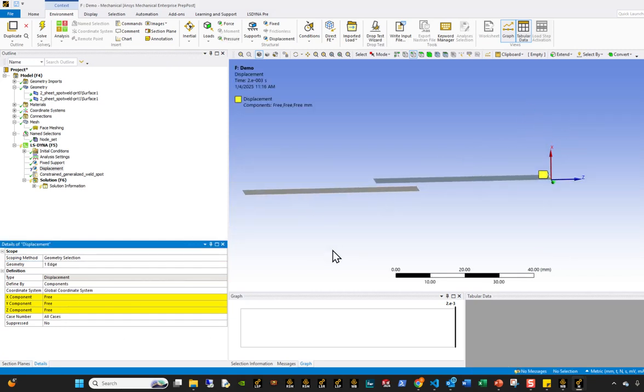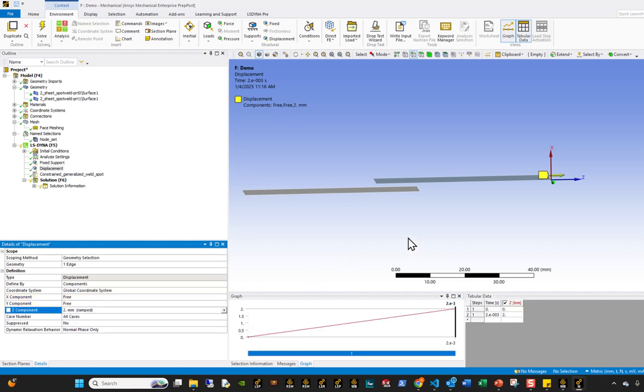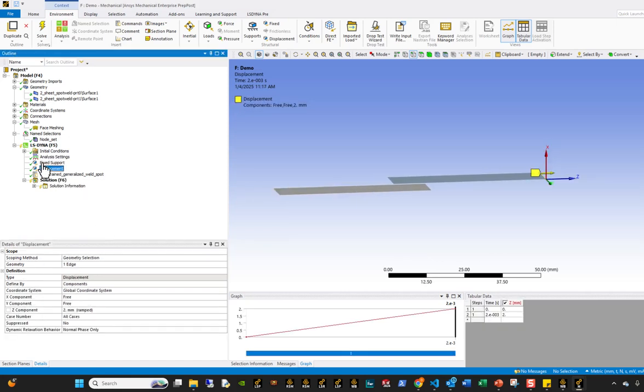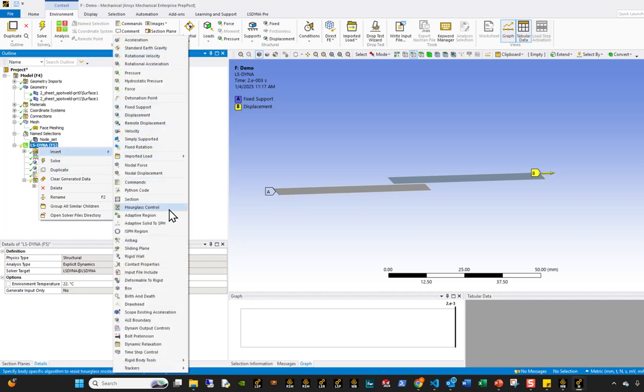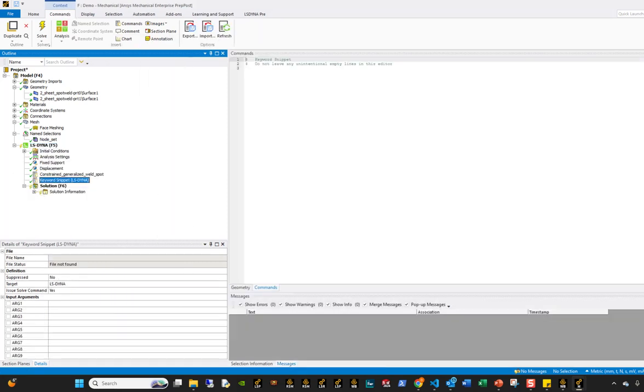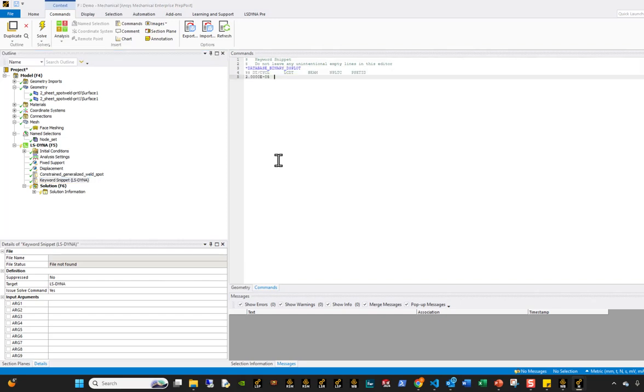And then in this case, I'm going to set the displacement to 2 millimeters, right? And then I'm going to add a database card, as I've done in the last problems. Very quick. Same thing, the database card is going to be the same one we used last time. I'm going to set about 1/100th of the termination time, give us 100 data points to look at.